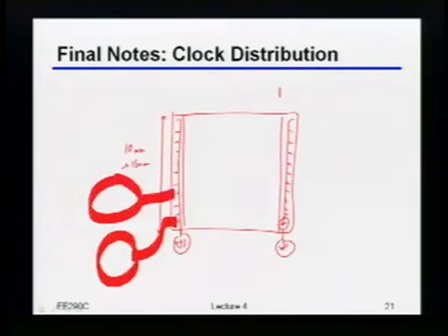how you figure out locally what's the right point to sample. A lot of that is also about distributing the clocks to all the different links that you need to be working with, because when you have to cover large distances and have these pretty high frequencies, and still maintain very low jitter, it turns out to be a pretty big issue. Okay? Any questions on this?